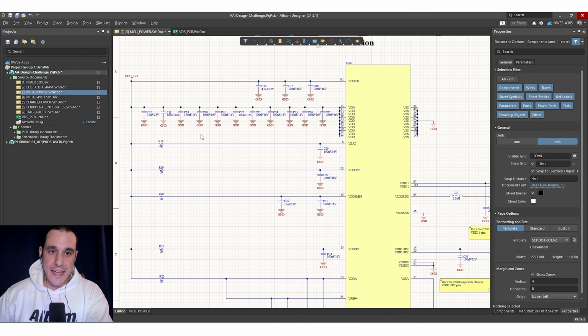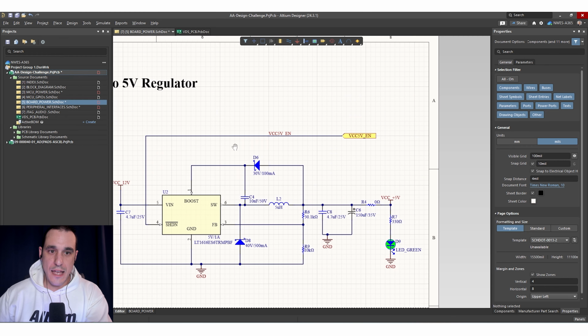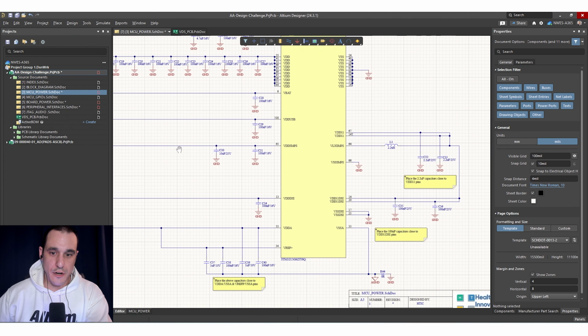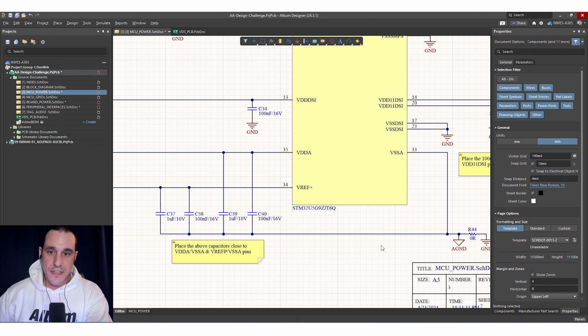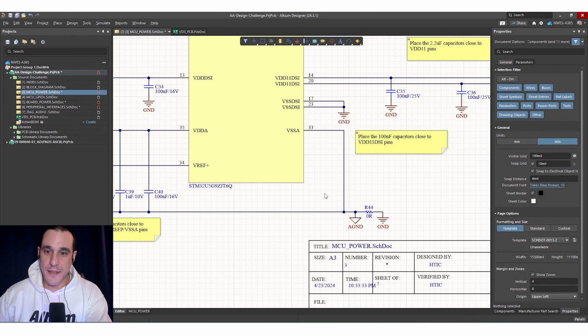Now, if you go back and look at the MCU 3v3 net and go over here to page 5, and we zoom over here to this regulator, you can see where this regulator is referenced, right? It's referenced to GND. And then if we go over here, we see there's this additional AGND net, and this routes over to the analog reference and then the VSS analog. So it's essentially the ground port for the analog supply.